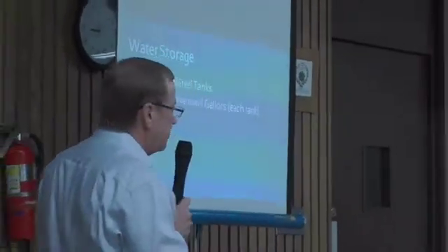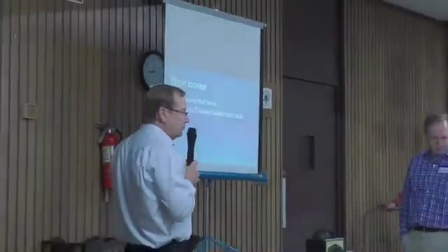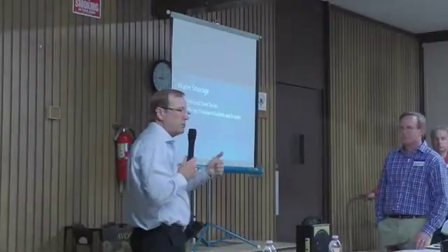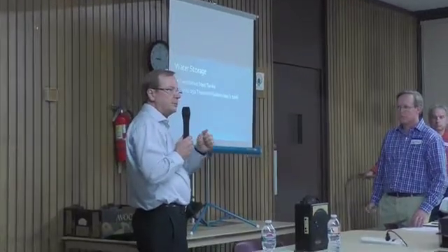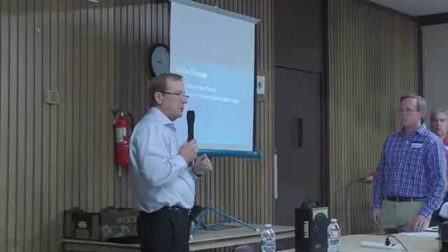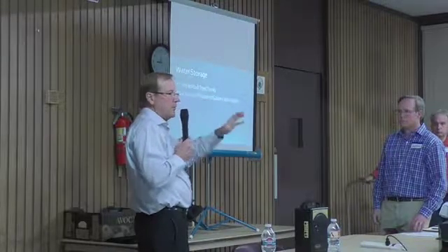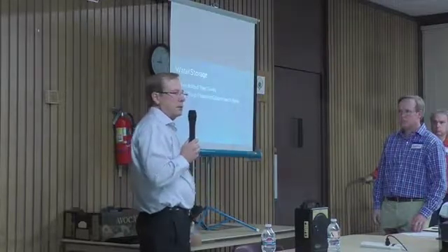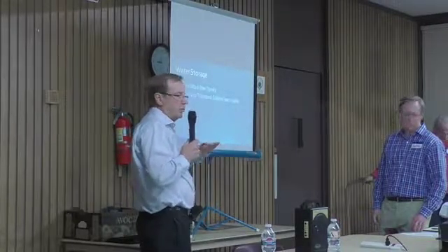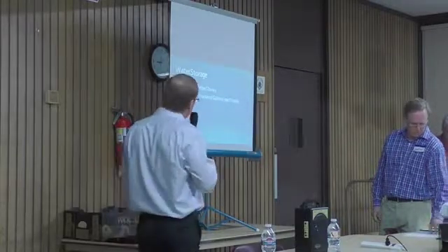The water storage facilities, right now, in order to provide for the state mandated storage, which is equivalent to your maximum day demand, the state wants every community to have at least one day's summertime usage in storage, in case there's power outages, what have you. They want at least that much storage for a community.